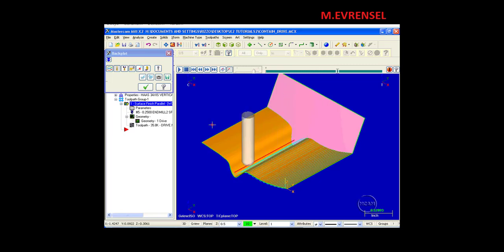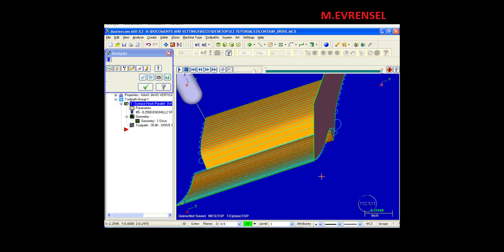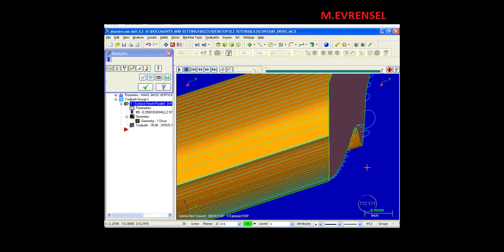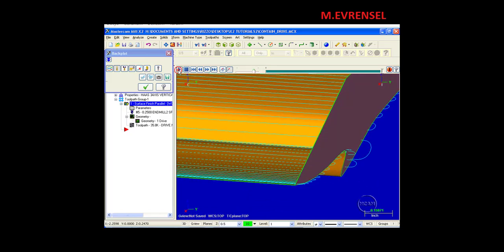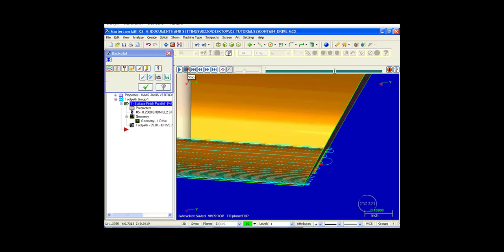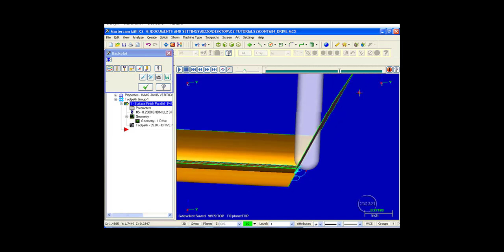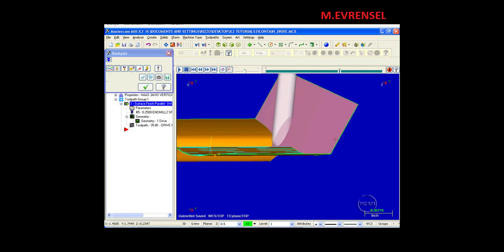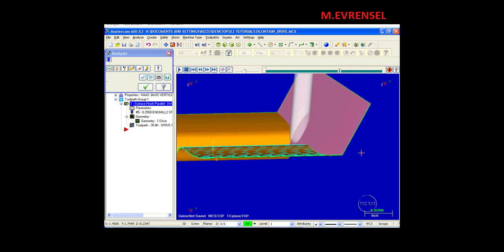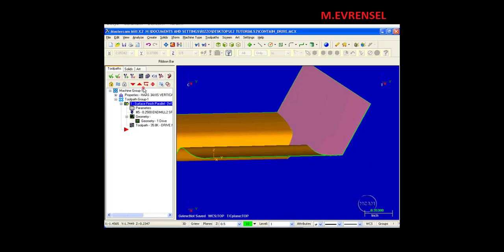And there's our one drive surface being machined pretty much as expected. However, upon closer examination of the intersection between these two surfaces, we can see that the tool would be colliding right through this planar surface here. Let's run that again from this view and take a closer look. And we can see very easily there that the tool is driving right through this surface. So what this toolpath needs is a check surface, which by definition is a surface that will not be machined.